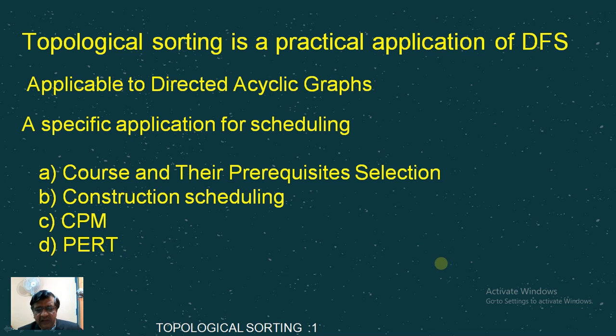And then it could be construction scheduling. First of all, the earth is to be dug and it should be ready for foundation. Then foundation will start. Parallelly, we can start carpentry work, and then comes curing, and then comes construction of the masonry, something like this. If we attach the time taken before the start of the next event, it becomes a problem of great significance.